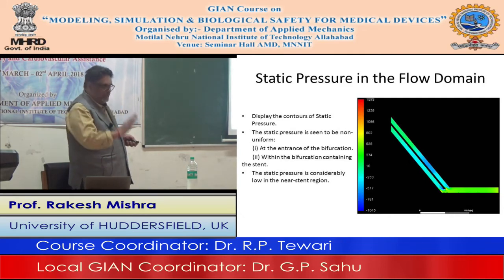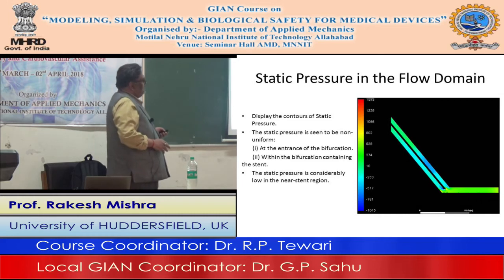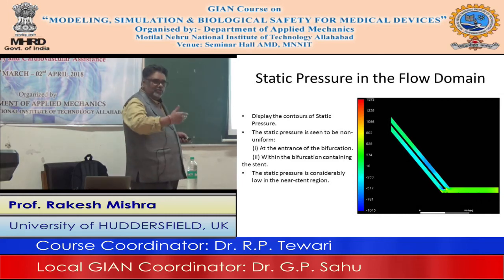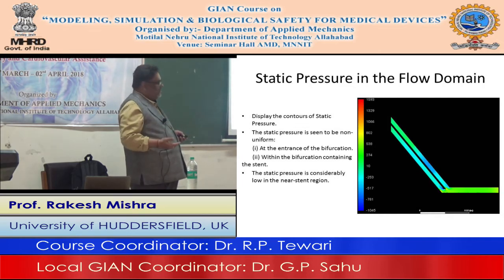So typically in a fluid flow, this is the first thing that you explain, the pressure distribution, because pressure distribution tells you how you're losing pressure, how energy is being dissipated, how total energy is decreasing in the forward direction. That's why you're losing pressure in this particular direction. Okay.